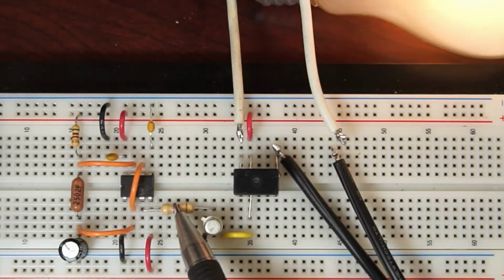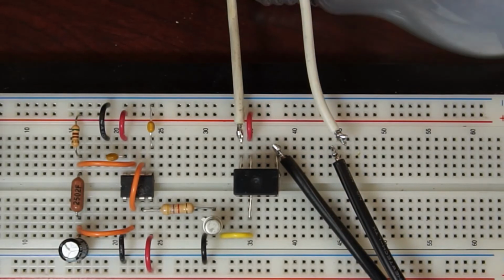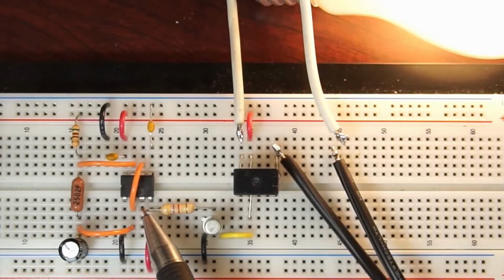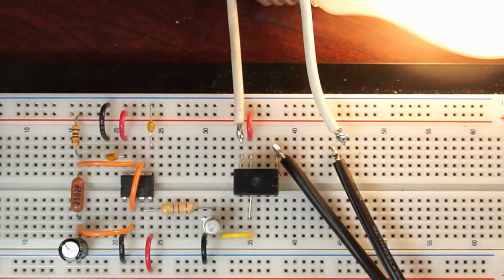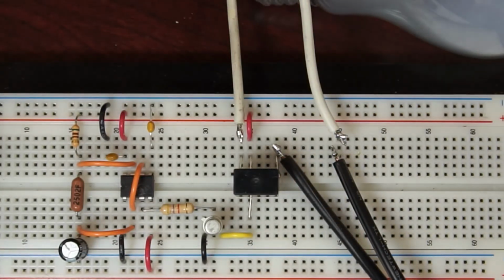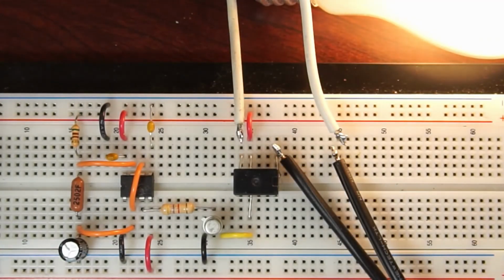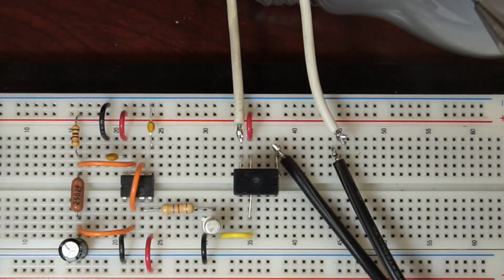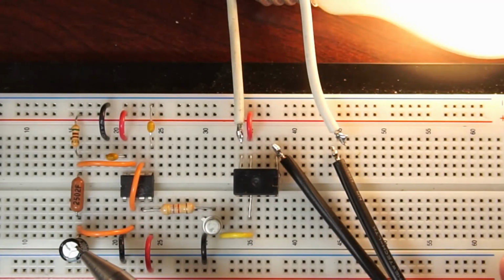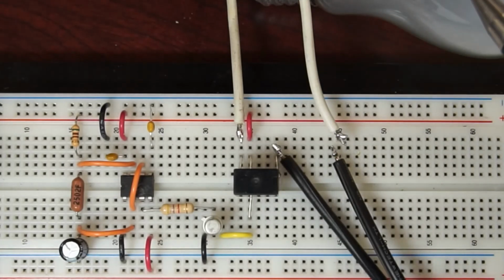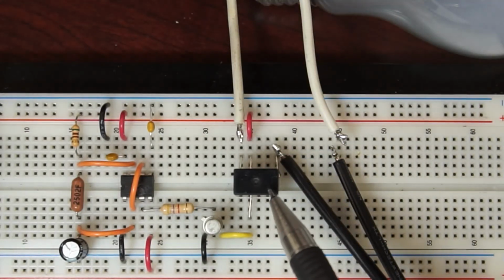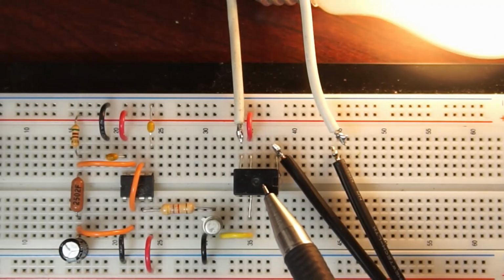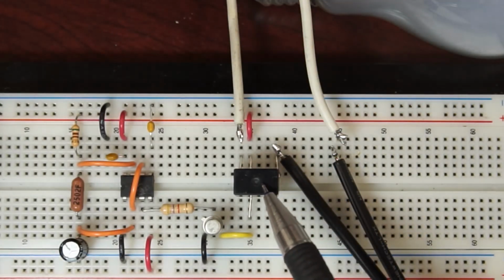The 4.7K base resistor carries the square wave from pin 3 of the chip over to the base terminal of the transistor. You may have noticed that when I inserted the red wire, it took a couple of seconds for the timing capacitor to charge up and begin the flashing of the light bulb. You may actually be able to hear the contact inside the relay switching on and switching off.